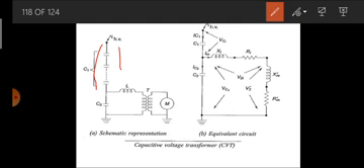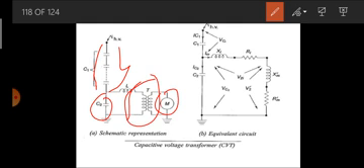The total capacitance of the voltage transformer will be almost equal to a few thousand picofarads. Then we have a matching transformer which is connected between the load or the meter M and C2.